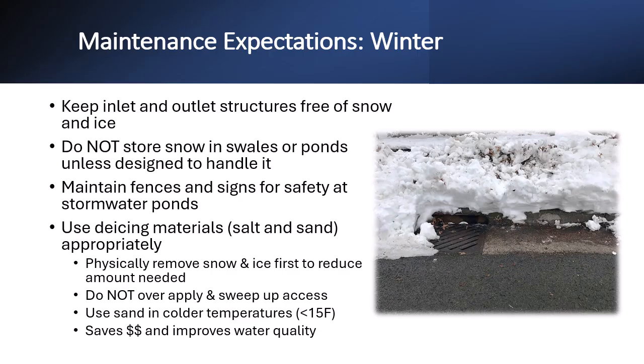Use de-icing materials such as salt and sand appropriately. Physically remove snow and ice first to reduce the amount needed. Do not over-apply, and sweep up excess. Use sand in colder temperatures, such as those below 15 degrees Fahrenheit. This will save you money and improve water quality.